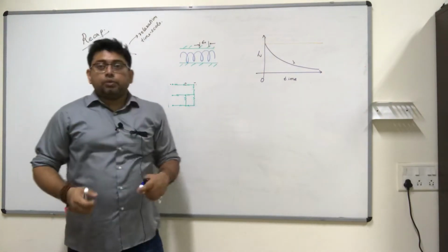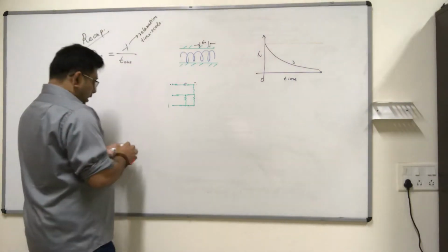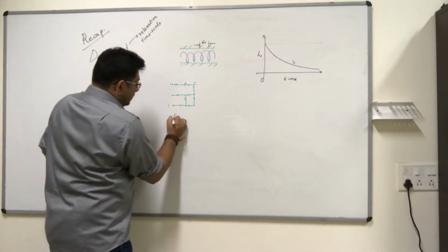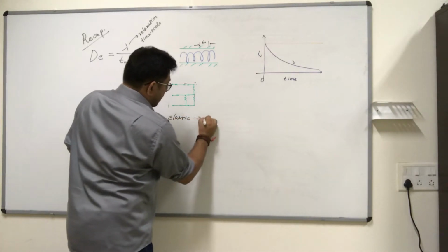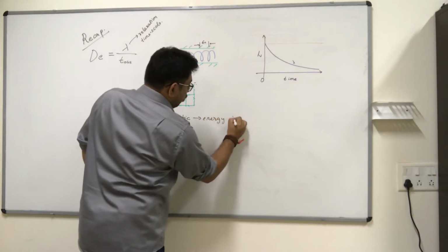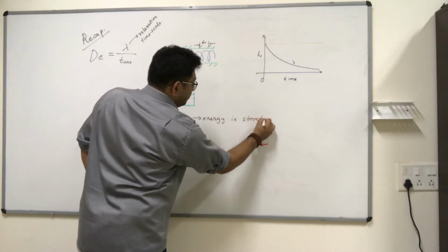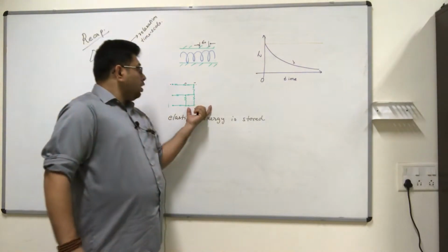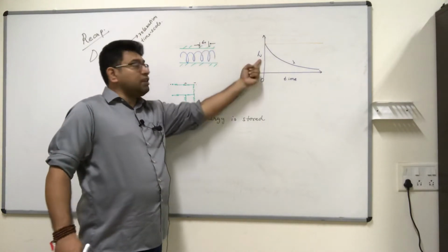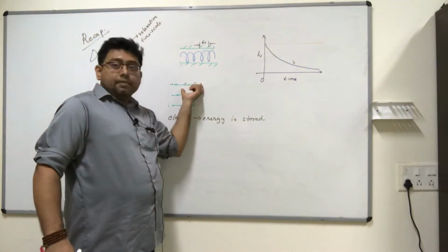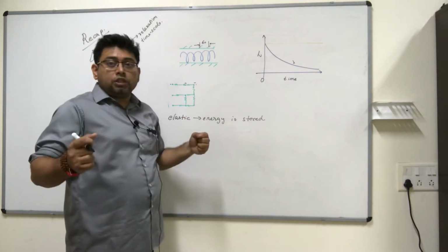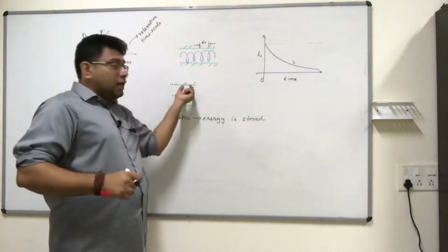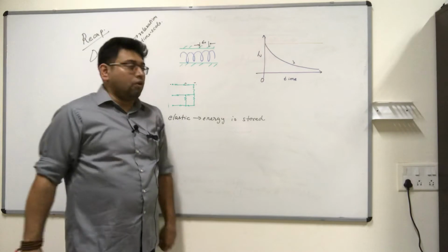So in a solid body, that's why we say in an elastic body, energy is stored, because to keep this epsilon naught, you have to keep this amount of stress, and the atoms or the molecules have been displaced from the original position and you're holding them there, right? So all these springs can be thought of as stretched, being in the stretched form.